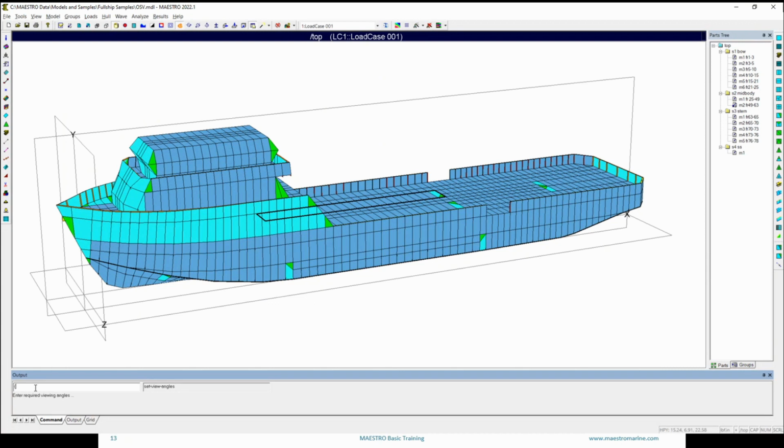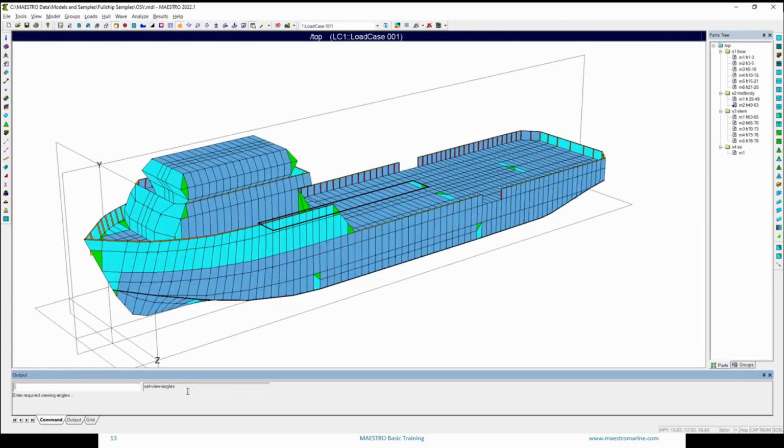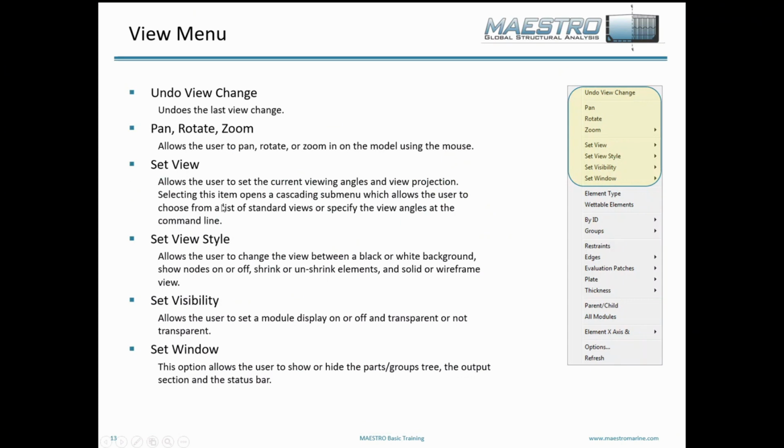And then here it's asking for, say, 30, and we can close the brace if we want, but I think it'll do it automatically if you don't. And it goes to that angle. Now, it didn't echo the rest of it in there, but that's essentially what the set view command does.